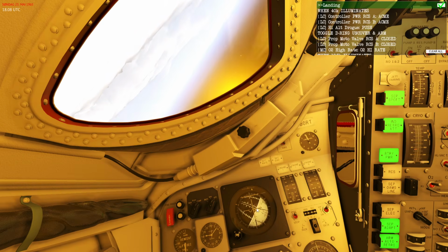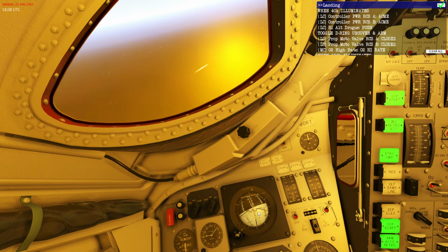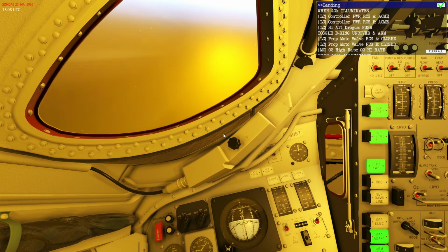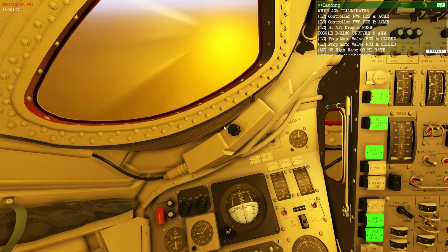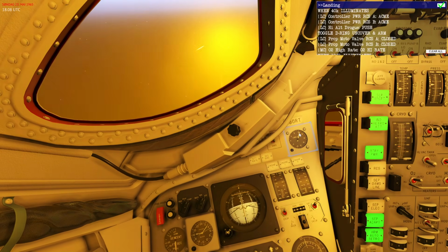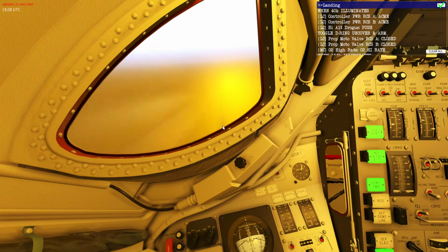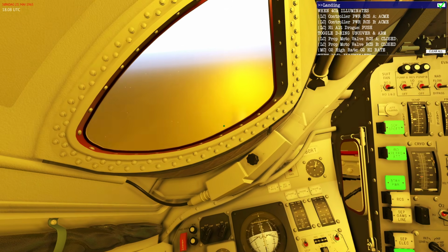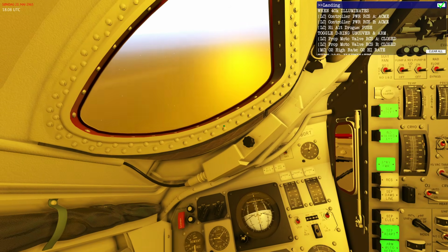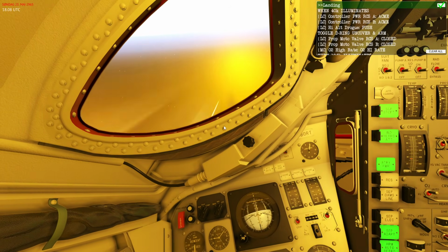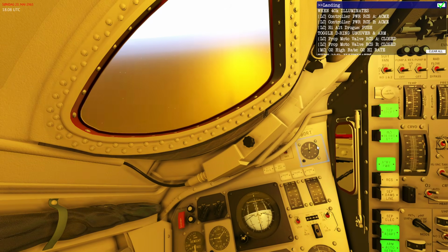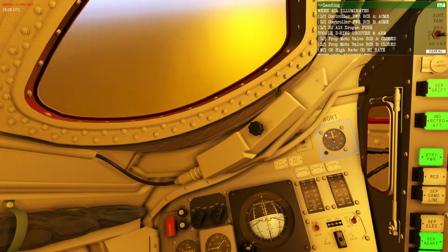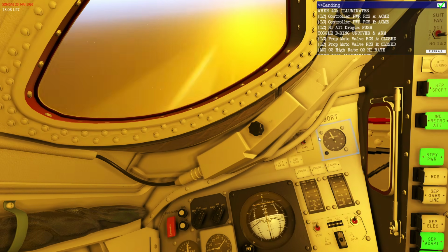Now you will see that once the lift vector points upwards, so now we have heads down, lift up, this G is now going to stop, and then it's going to slowly go backwards towards 3 and so on. If I would have stayed in the other attitude, which means lift vector down towards Earth, I would have exploded by now. I was a little bit late on my roll, so I started the roll at 4.5 Gs, and you should start it at 3.